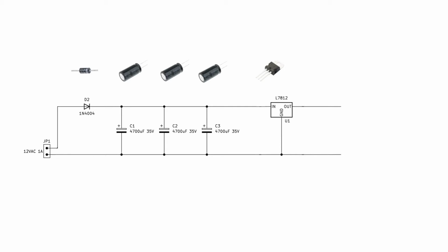But again, we are not quite there yet. Sudden increases of the load can result in a momentary drop of the voltage. The big capacitors are too slow to handle those, so we must add some smaller capacitors at the input and output pins of our voltage regulator. These are often called decoupling capacitors and they must be mounted as close as possible to the in and output pins. We must keep that in mind when designing the PCB. I will use tantalum capacitors for that.